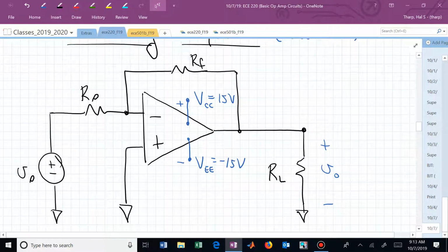It's maybe a little bit more challenging to see meshes in this diagram, but what if, in step 2, we concentrated on learning how the currents are responding at that particular node? Can we write a KCL equation at the inverting input pin?